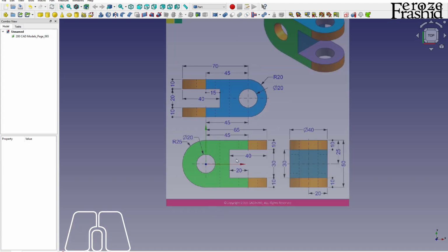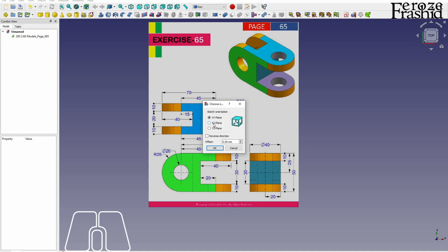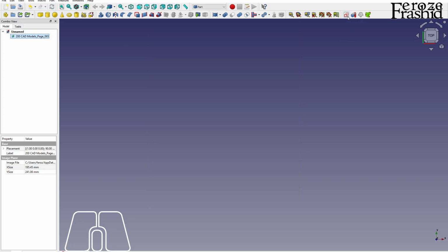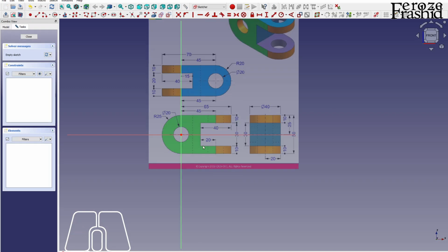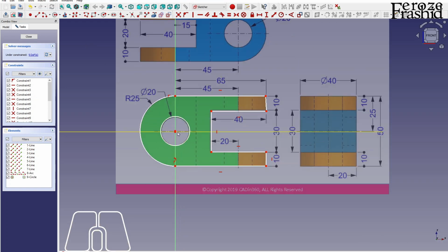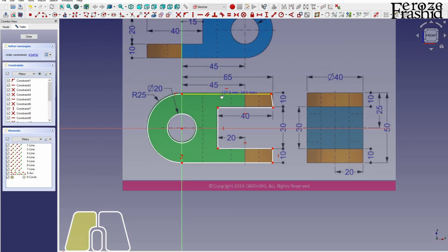All right, now I want to do it from this face, so on the front face. So my first sketch would be on the XZ plane. Before that, I'll have to move this image to the XZ plane. Now I'm going to go ahead and make it on the XZ plane. So tracing the image is done.